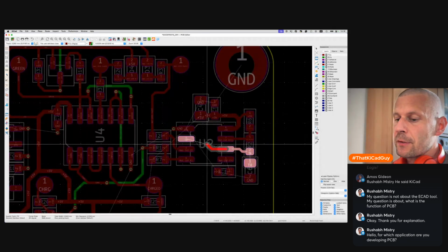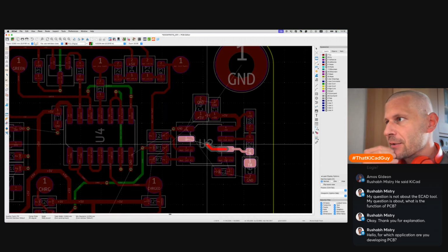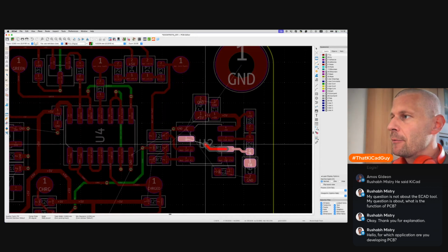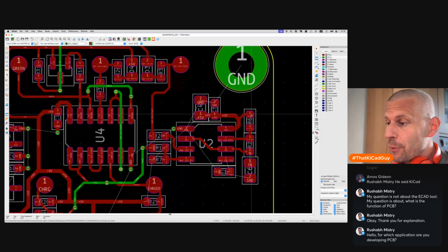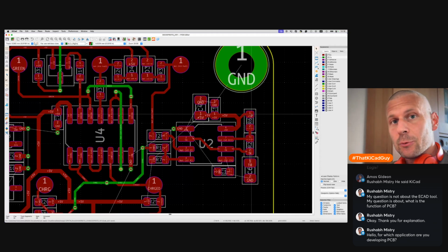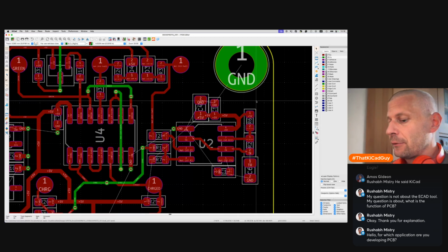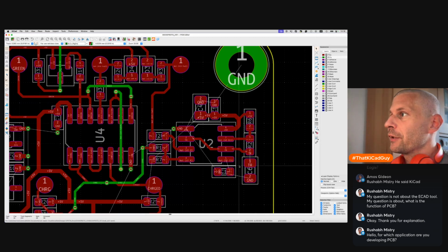The same with the 555 astable multivibrator. It's a verified circuitry, and I can place the track below because I will not change the circuitry here, just the values of the components. This is why the components are far from the package, to enable me to manipulate with the soldering iron tip and give me some flexibility.